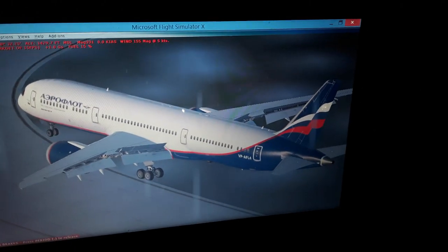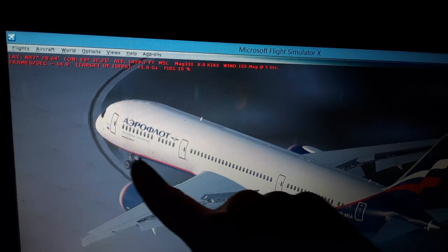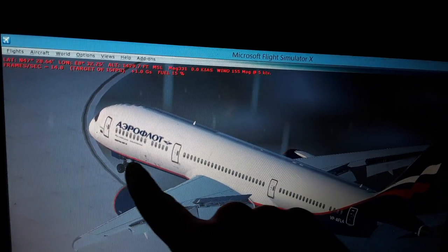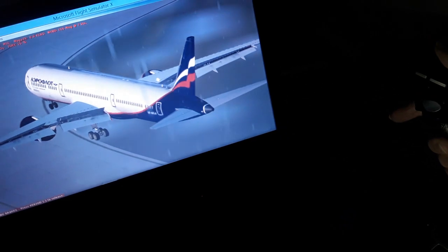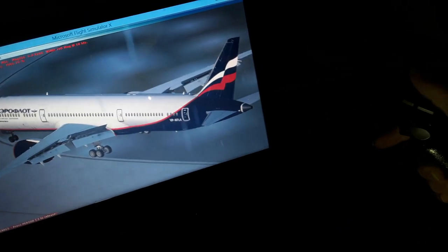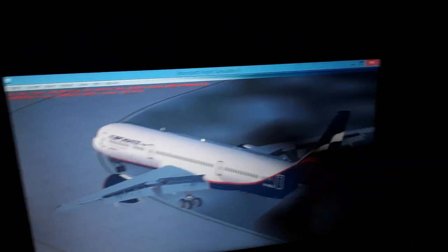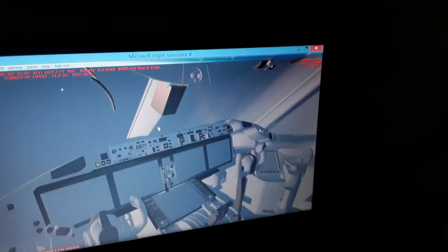So from the computer automatically, the forward nozzle steering will decrease from 76 degrees left and right deflection to 7.6 degrees. It will be limited. So above 45 knots, up to 80 knots, we have 7.6 degrees together with the rudder, when we press the rudder pedals like this.